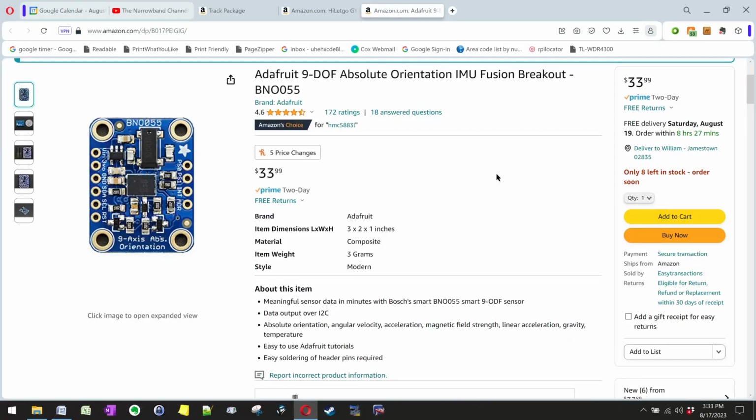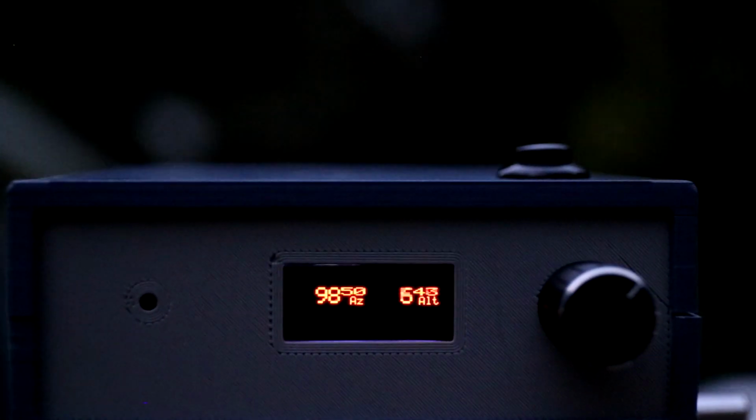The azimuth and altitude values are measured by the Adafruit BNO055 Absolute Orientation Sensor. It's likely that the platform for the compass won't be stable enough for arc-minute resolution to be appropriate, even though the sensor measures to the arc-second. This is freehand, and I'm trying to acquire and hold 150 degrees azimuth and 40 degrees altitude, and I'm just not able to. Even on a tripod or attached to a Dobsonian telescope, the tripod, or scope, would likely be hand-operated. Arc-minute precision would be optimistic. Arc-second resolution would be pointless.